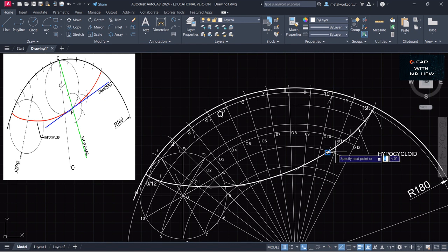So we're going to go to layer 5 and draw a random line. All right, that is the point P. So let's label it now. P, single line text. We're going to make it 6 millimeters the height. This is capital letter P. All right. Now layer.